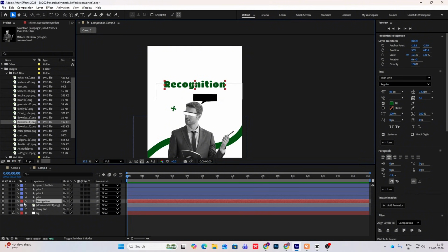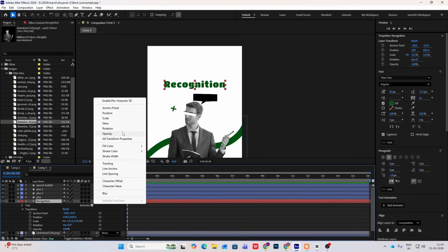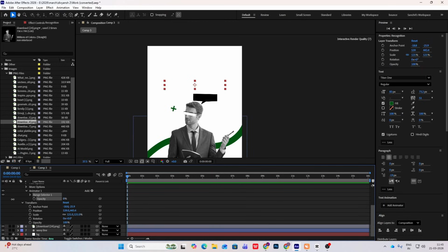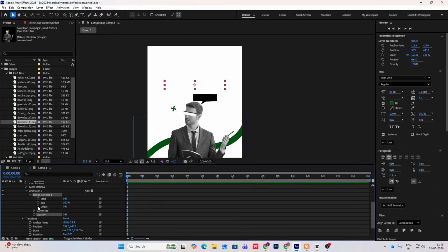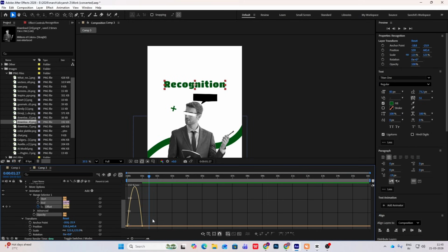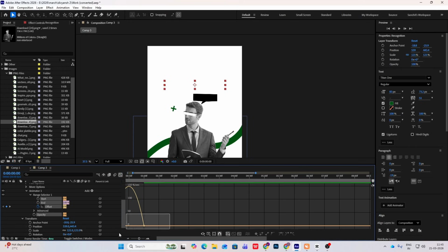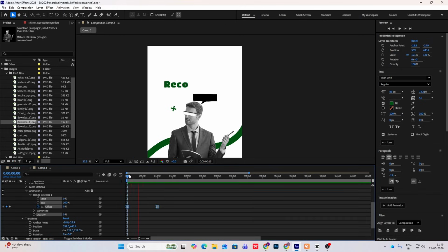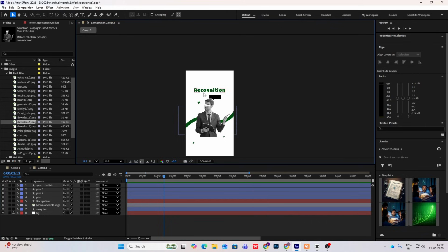For this, simply open this up, animate, opacity, bring this to 0, open this up, click on the offset, go ahead, again click on the offset, go to the end and make this 100. So you get this simple animation. Select this, F9, and bring these a bit closer like this. So we have got this text.